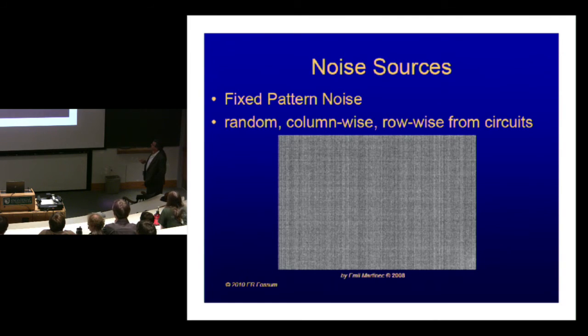But fixed pattern noise is just very subtle variations between elements in a circuit. When you have a large number of rows and columns, if you have some sort of driver that's driving the row, and that driver for this row is a little different than the driver for that row, or the sense amp for this column is a little different than the sense amp for that column, there's just a very, very slight difference. But your eye, unfortunately, is a very good pattern recognizer. So even though the absolute value of the fixed pattern noise is small, wow, you pick it up right away. You can all see both horizontal stripes and vertical stripes. If you actually went and measured it, you'd find it's not very big, but unfortunately for us photophiles, I guess would be the right word, wow, it's a big problem. It's a big problem when you're making big circuits.